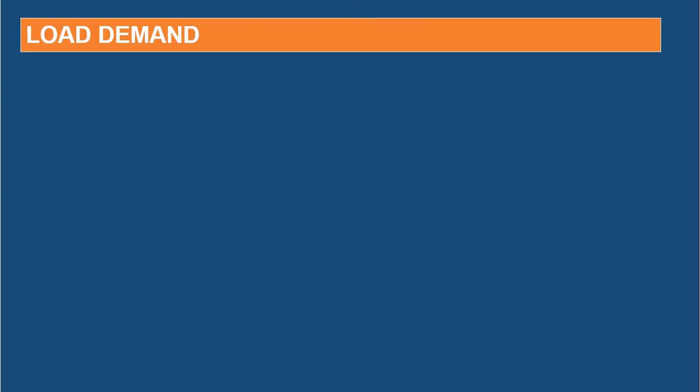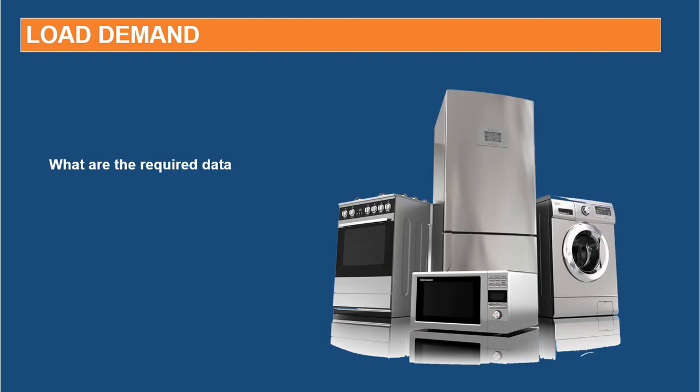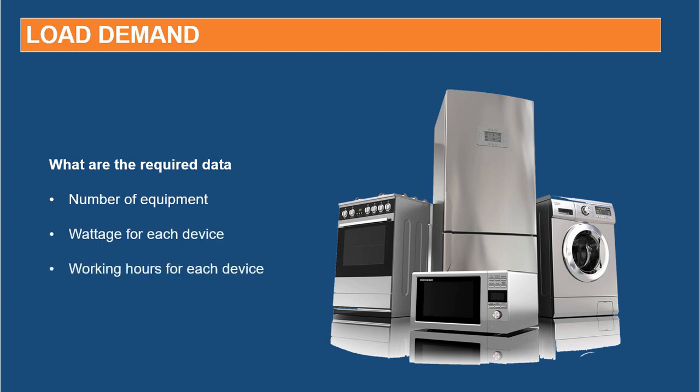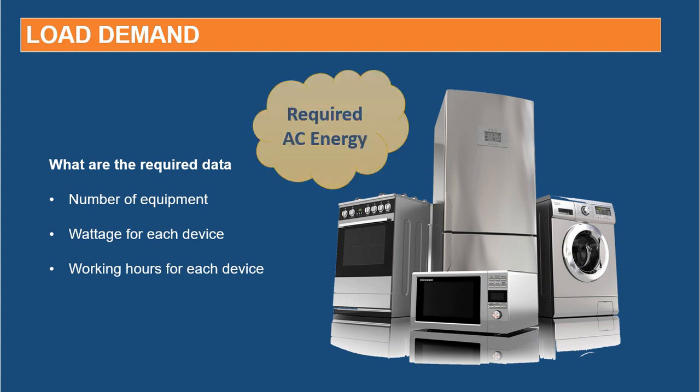If we come to the first one, load demand. Here we need to know 3 important things. The first one is the number of equipment, the wattage for each device, and the working hours for each equipment. This is for the purpose to get the required AC energy.